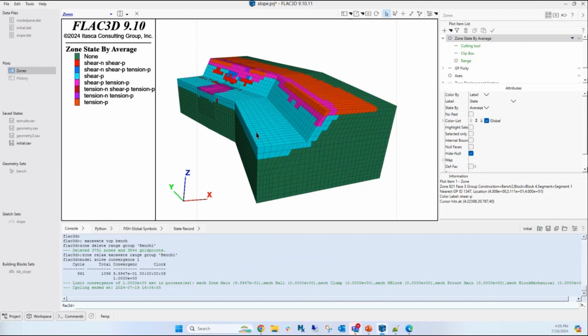This is a perfectly plastic material. So what will happen is that the stresses will go up and hit the envelope, and there might be failure. The stresses will be redistributed, and then the stresses will reduce, and so it's no longer failing, right? It will go back to being elastic. So all these things that failed in the past, maybe we don't care about that much.